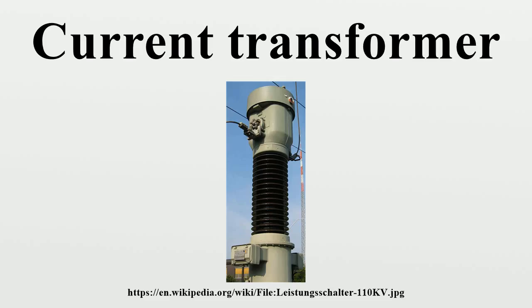Live tank CTs are useful because the primary conductor is short, which gives better stability and a higher short-circuit current rating. The primary of the winding can be evenly distributed around the magnetic core, which gives better performance for overloads and transients. Since the major insulation of a live tank current transformer is not exposed to the heat of the primary conductors, insulation life and thermal stability is improved.